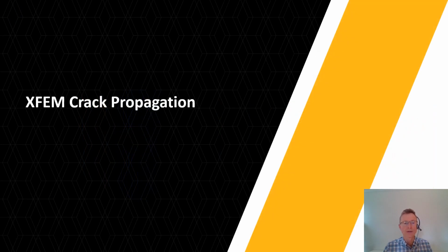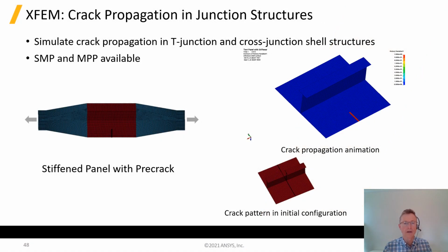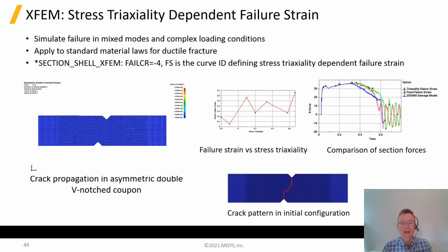And now on to XFEM. There are a number of improvements here. One is the ability to propagate cracks through T-junctions in the mesh. In terms of the initiation of failure, there's now an option for a triaxiality-based criterion, which gives a more realistic crack path.